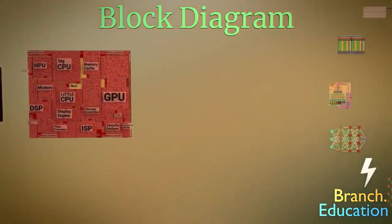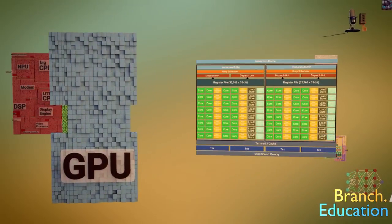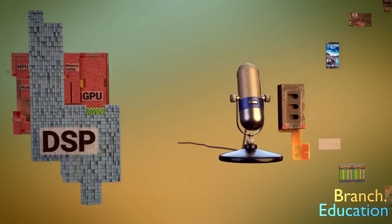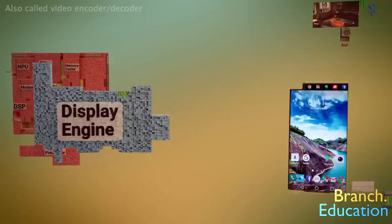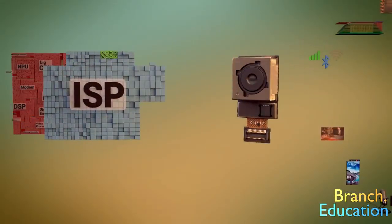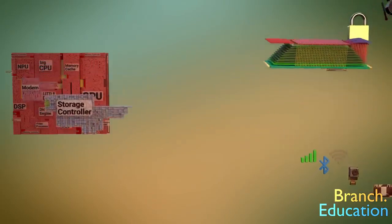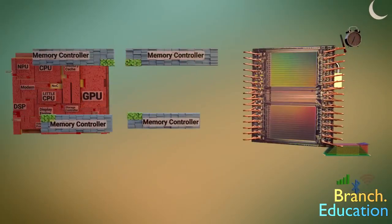The key areas in the SoC are the CPU containing multiple cores, the GPU which renders graphics, the shared memory cache which is usually around 4 to 8 megabytes, the digital signal processor which interfaces with things like the speakers, microphones, sensors, and many other things, the display engine which communicates with the touchscreen display, the video processor which compresses and decompresses images and video and enables 4K video recording and playback, the image signal processor which processes pictures and video taken by the cameras, the modem which interfaces with the various wireless networks, the storage controller which saves and loads information from the flash storage microchip, the memory controller which connects to the DRAM microchip located on top of this one,